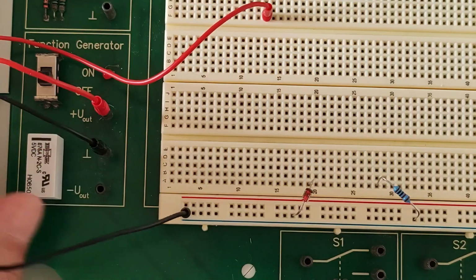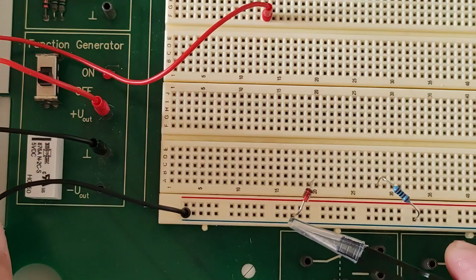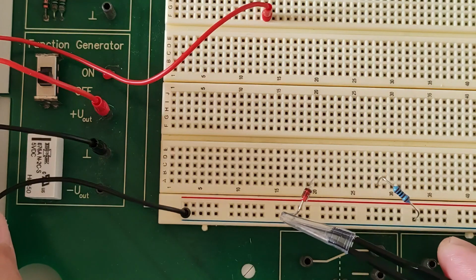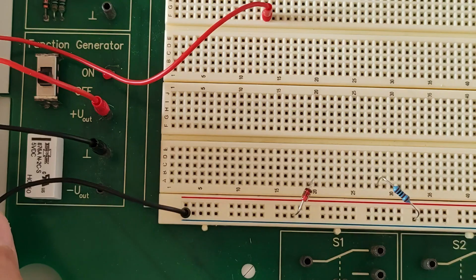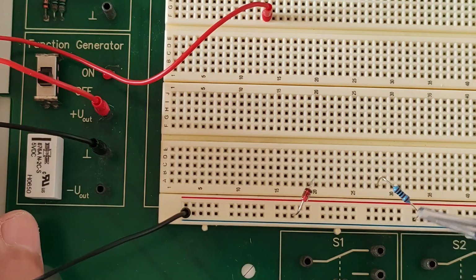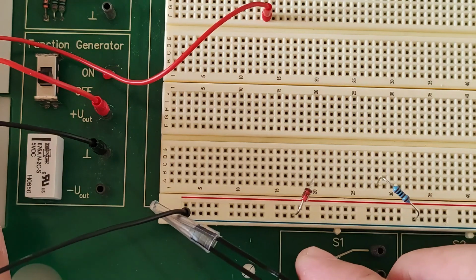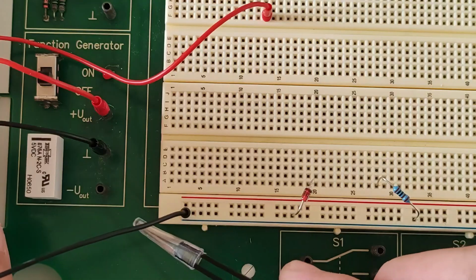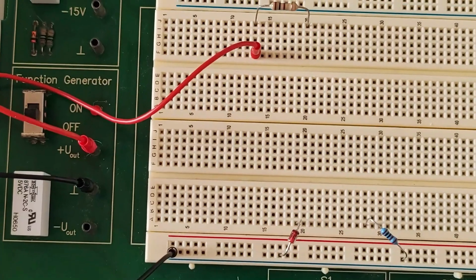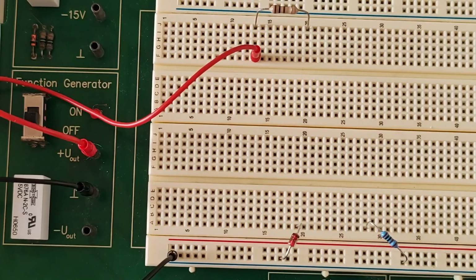Now notice that the anode side of our Zener diode is connected to ground also. And one of the legs of our load resistor, the blue resistor here, which is the 1 kilo ohm resistor, is also connected to the ground terminal of our power source, similar to the schematic diagram we saw earlier.